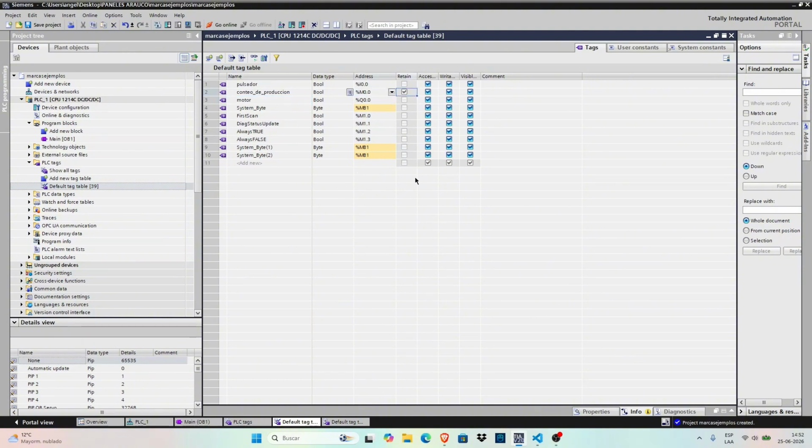Well, the retentive, from what I told you, that for example, if the PLC turns off or there is a power outage. The production count, let's assume that there are 7,000 shells counted. If the PLC is turned off and turned on again, those 7,000 will still be stored in memory, and 7,000 will still be output. But if I didn't have the retentive on, it wouldn't come out, it would go out to 0. Or it would start at 0.